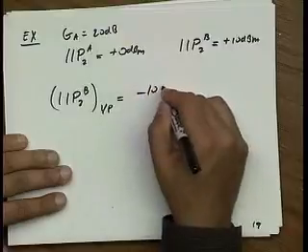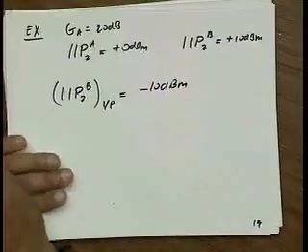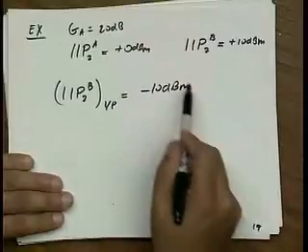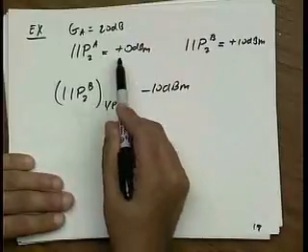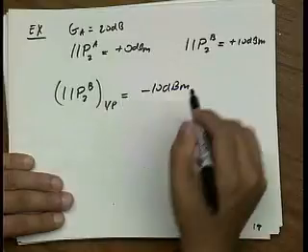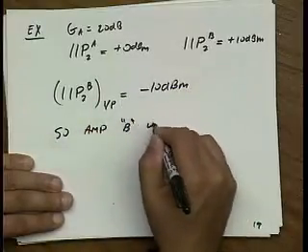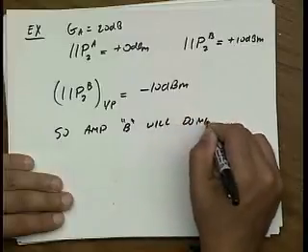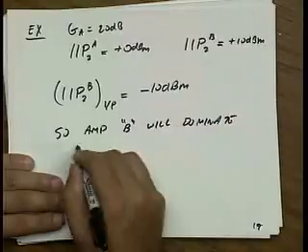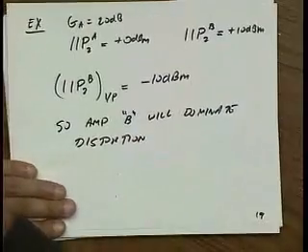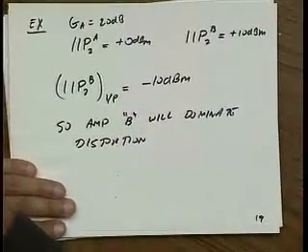It becomes minus 10 dBm. So you can see without really doing much math that because the IP2 input referred of this guy is 10 times the IP2 of this point, this will dominate. So amp B will dominate distortion. Is that clear to everybody?